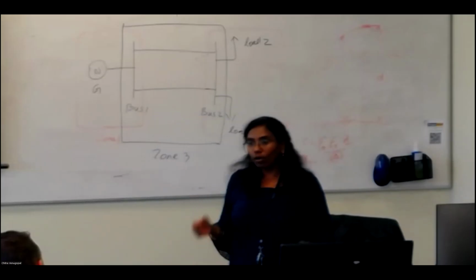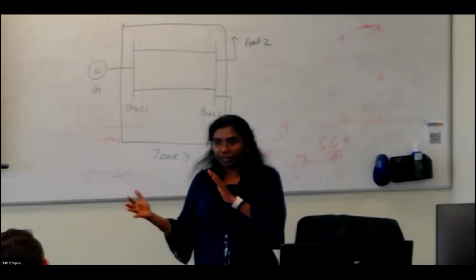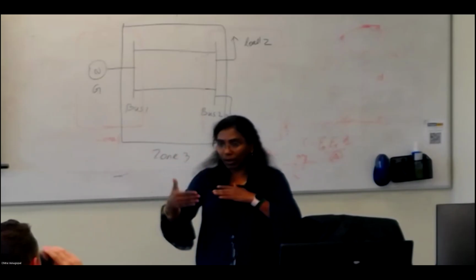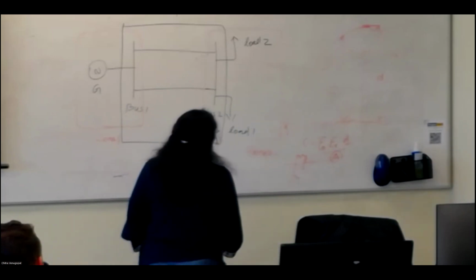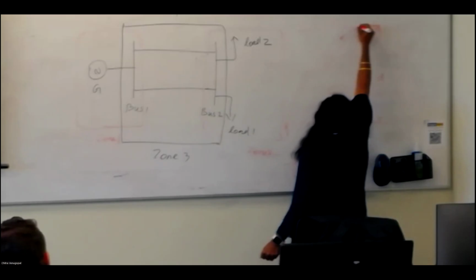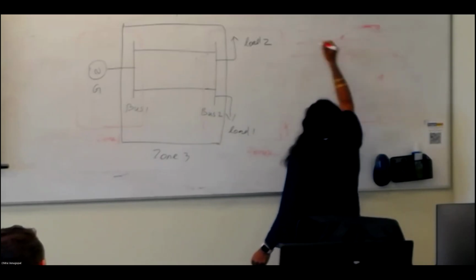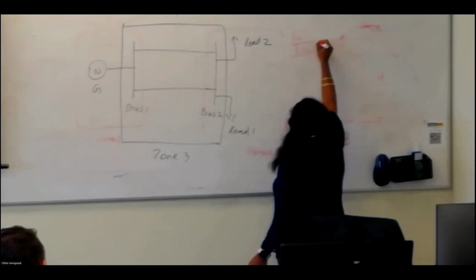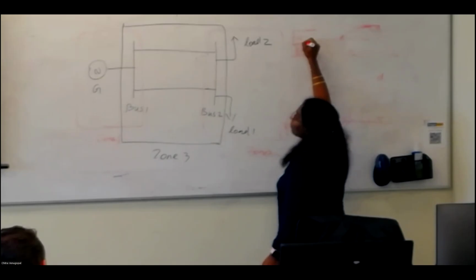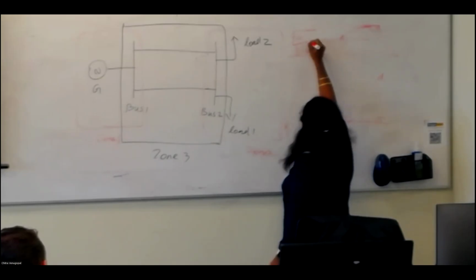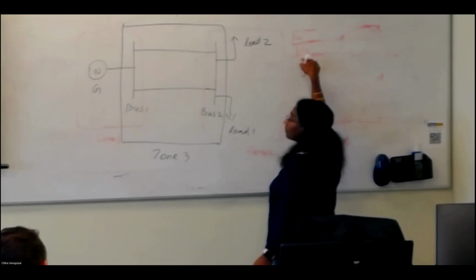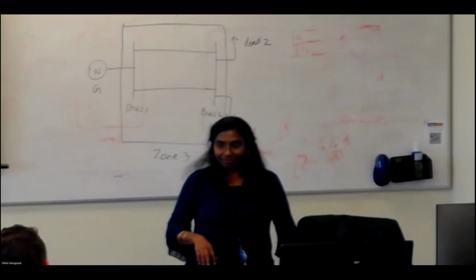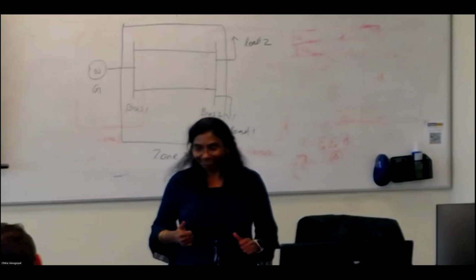Okay. And also between the two wires, there will be a capacitance formed. So when you are laying out the parallel lines, you also need to calculate the capacitance between the two wires, because when you are talking about the parallel wires, the wires will be flowing like this. So there will be capacitance C1 and C2. Because this is a charged wire, this is a charged wire, the distance between the two will form C1. This is another charged wire, this is another charged wire, the distance between the two will be C2. So we have to calculate that capacitance and put it here. Okay. Line to line. Line to ground.